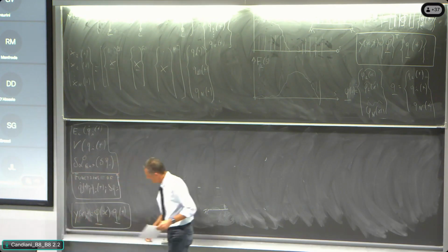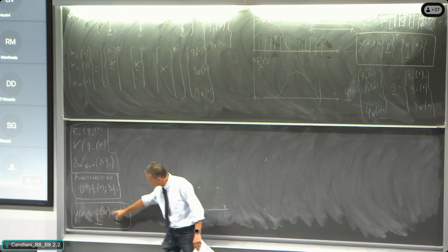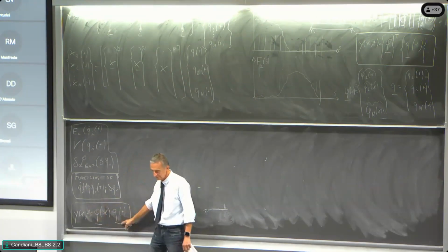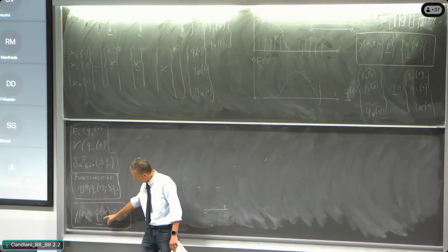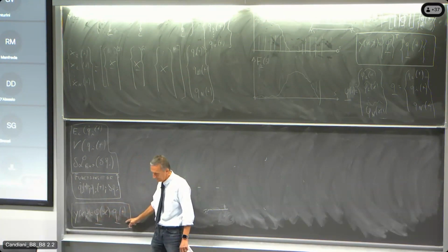So the statement is this one. First, we are representing the time-space distribution of the movement of the structure through this position. The eigenfunctions are known, the principal coordinates are unknown. This is the new unknown of the problem.